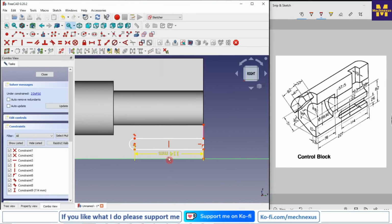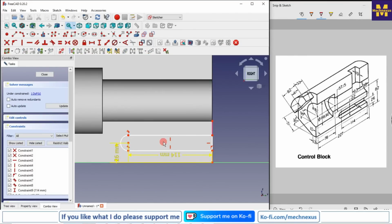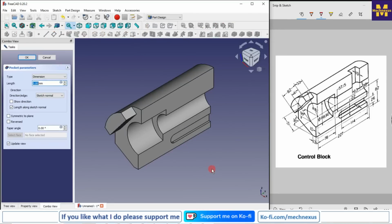This is 114, and position of this slot is 26 from the edge. So I will select this point and this point and give 26, and diameter is 22. So I will select this and I will give diameter 22. Now I will move my dimension outside. Okay, now I will give the cut depth 13, so I will go with the cut and give 13, and I will say okay.